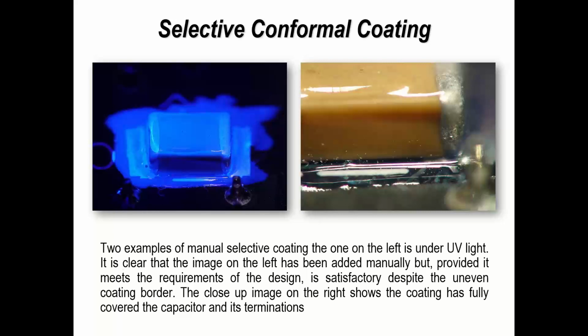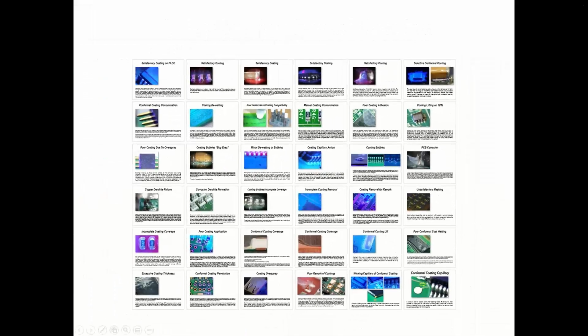And if you look at the right-hand side photographs, you can see the coating. The coating is around the parts. You can see it on the side, and you can also see it over the top of the capacitor as well. There are very few, very small voids within the liquid coating, or the cured liquid coating, but that would have no impact on the reliability of the product.